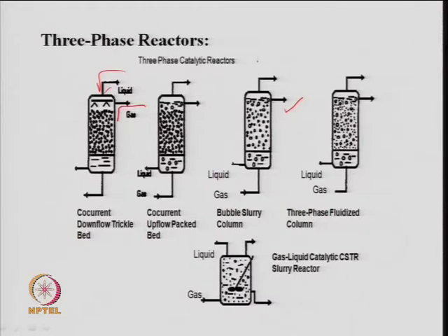Same thing here, this is a kind of 3-phase fluidized bed reactor. So, you have the solid inside the bed, you have the liquid, which can be in the form of suspension, and the gas is being passed from the bottom continuously. So, gas comes out, liquid goes in, liquid comes out along with the product, and you have to decide what level or how much liquid product is to be collected accordingly.